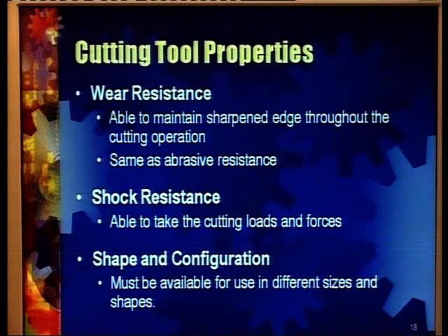In case the tool material at the cutting edge breaks off while we are machining, then again we will have to replace the tools, and in addition to the cost of that damaged tool, we will also incur the non-productive time of replacing and resharpening the tools, as the case may be.